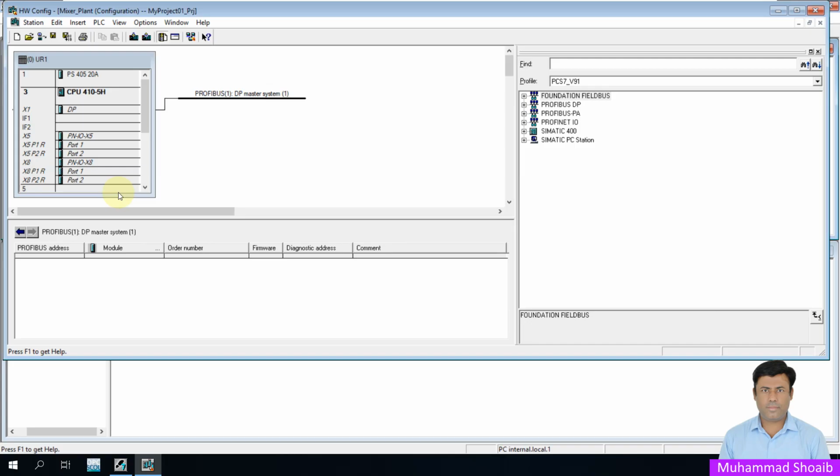After creating a multi-project with the PCS7 wizard, an AS station is automatically created. If you have selected the correct bundle, then the AS station in the hardware configuration will be exactly the same as your existing AS.